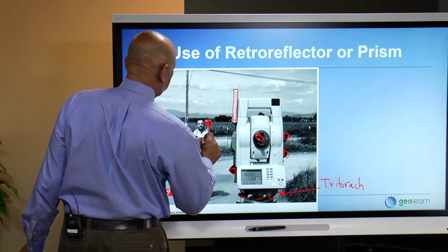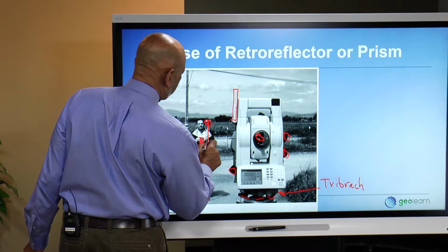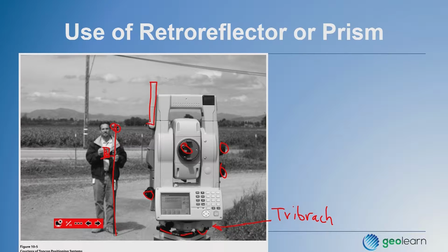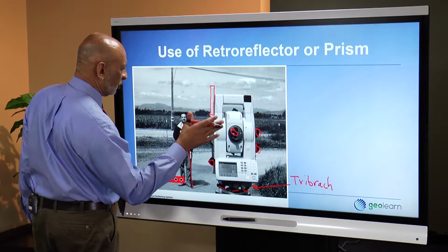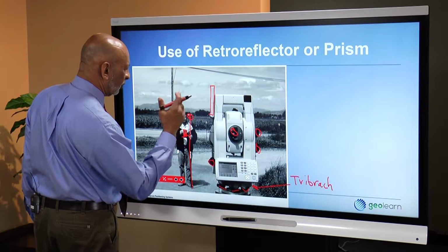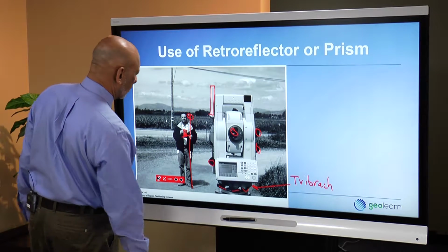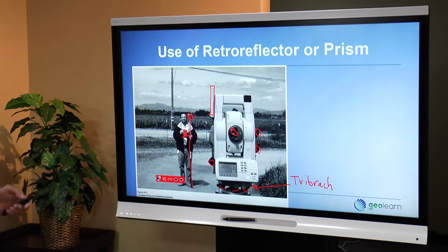And as the surveyor moves around, here's the field controller attached to the prism pole, simply presses the read key or take a measurement key or compute this function key, and depending on where the data resides, the data is used to compute things and can be used to turn the instrument from right to left or up and down, to either set out new points or to measure the positions of existing points.